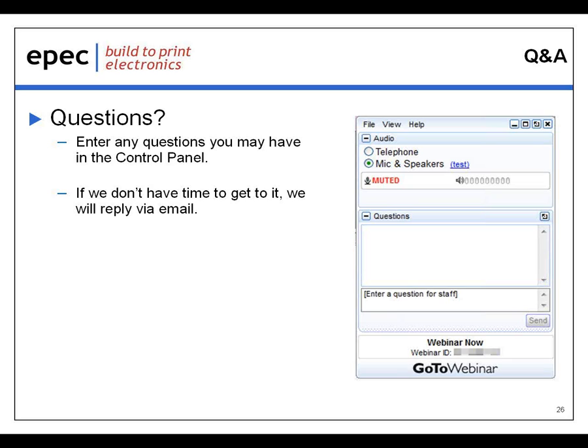For difficult environments, including shock, vibration, and wide temperature excursions, if we replace the polyester sheets with the screened conductors with a printed circuit board, and it could be a very thin printed circuit board, we can use soldered connections and stronger connectors, and we will have a very robust solution that supports long-term reliability. We can use thin printed circuit boards in place of the several layers of the polyester sheets with a membrane keyboard, including all the adhesive layers that go with it. And we'll still be in the same assembly thickness range as conventional flexible membrane keyboards. So that works out very, very well.